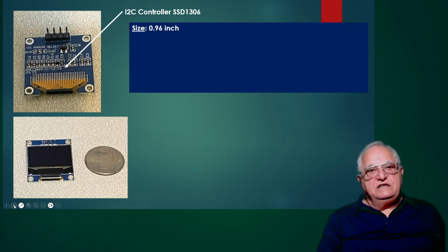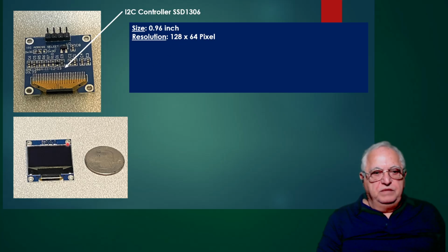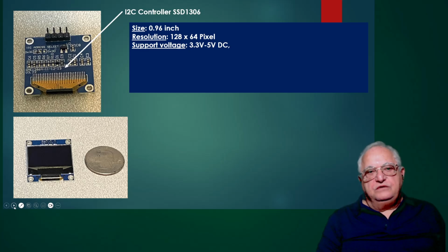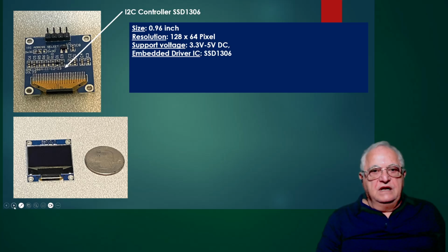So the size is 0.96 inches. The resolution, as I noted, is 128 pixels by 64. Next, the voltage: we're going to use 5 volts, but it should also work with 3.3 volts. Next, as I noted, the embedded driver is going to be the SSD1306.